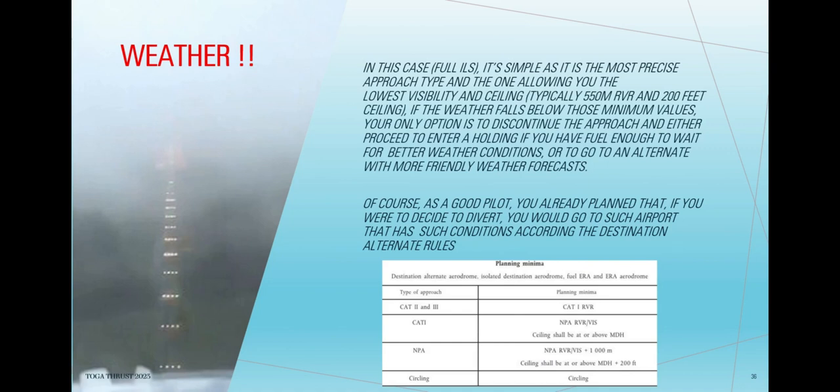Weather. In this case, full ILS. It's simple as it is the most precise approach type and the one allowing you the lowest visibility and ceiling, typically 550 meters RVR and 200 feet ceiling.